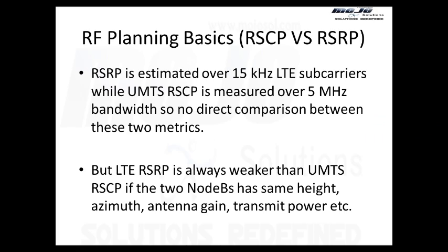We will do FDD LTE planning totally, because that's what is being used. FDD is being utilized and deployed everywhere. TDD we only use where there's a shortage of spectrum and we don't have bandwidth for uplink. So what we do is combine uplink and downlink in the same channel, and we call it TDD. TDD is deployed in very few places. I have never worked on TDD personally, neither UMTS nor LTE, nor can I recall where it has been deployed.